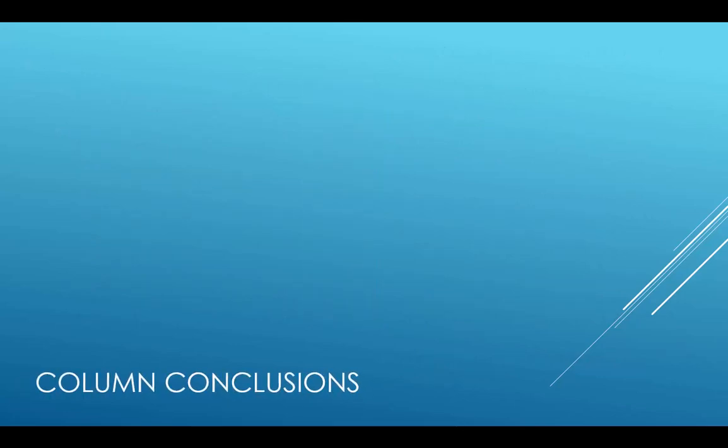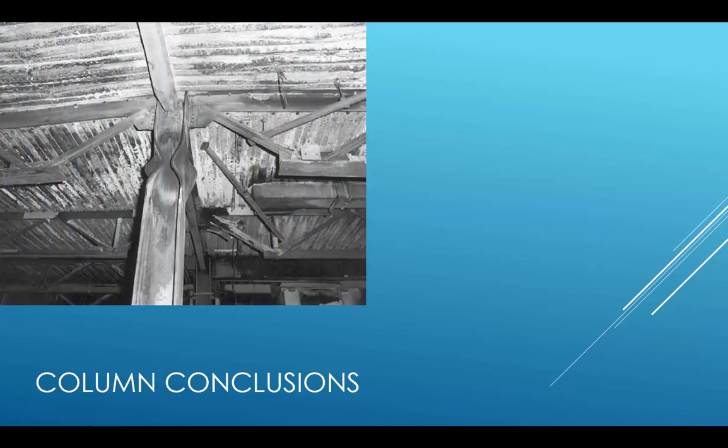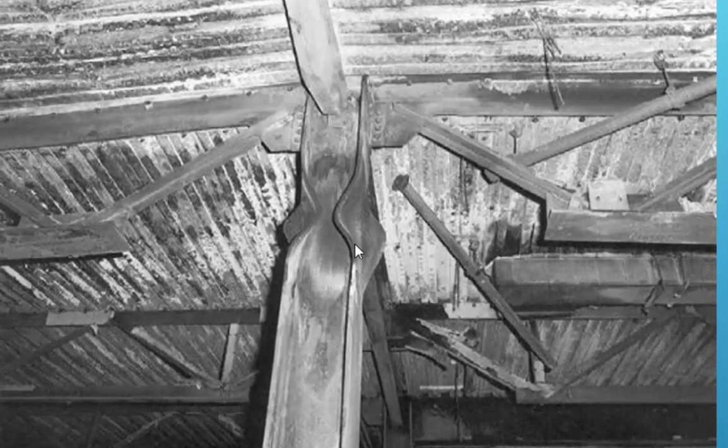Finally, I wanted to mention a couple of examples here. This is an interesting picture of a column. Notice how this is failing in the direction that we are facing, not left to right, but forwards and backwards. This column is a wide flange shape, but it is weakest in that plane. So it clearly shows right here that it kind of flared out, it was buckling over in the weak plane.